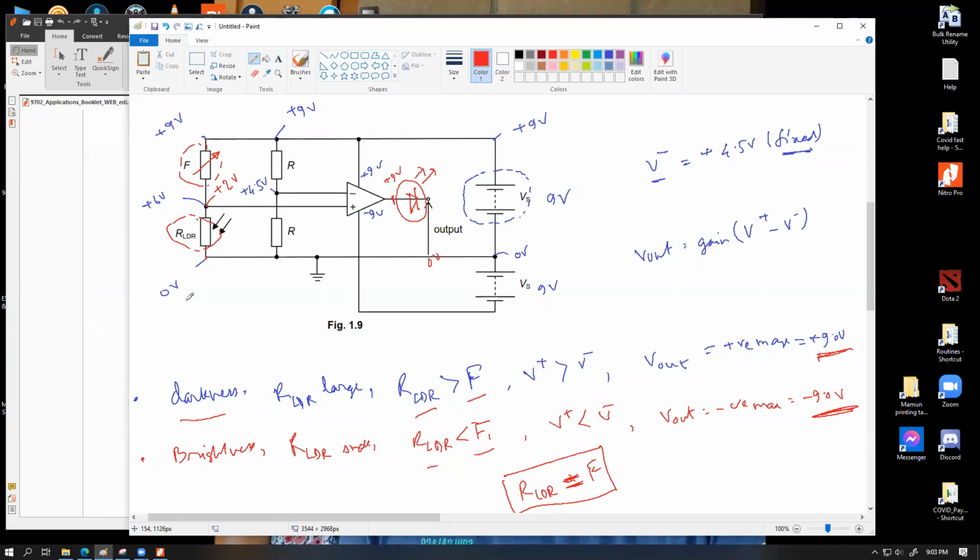So you can actually fine tune the exact sensitivity of this LDR, that exactly for what value this swap between big to small or small to big should happen. And to make sure that we have that flexibility, we can attach a variable resistor in this place, which can make this whole circuit usable for a wide range of users.